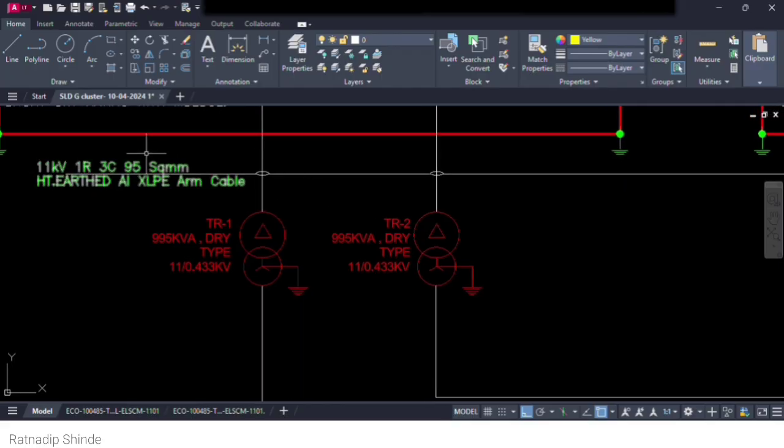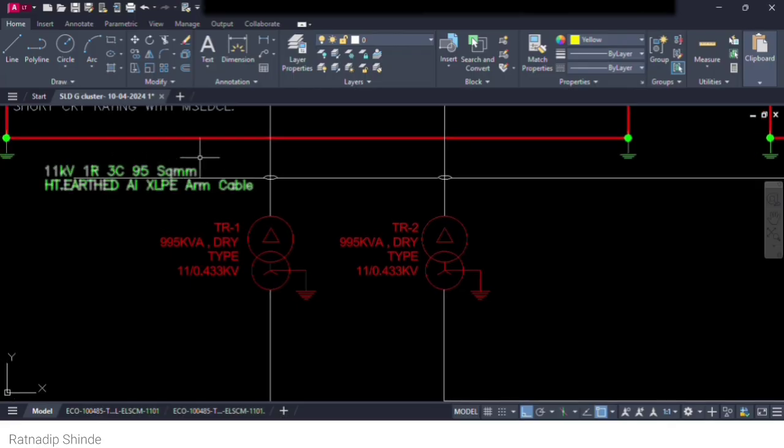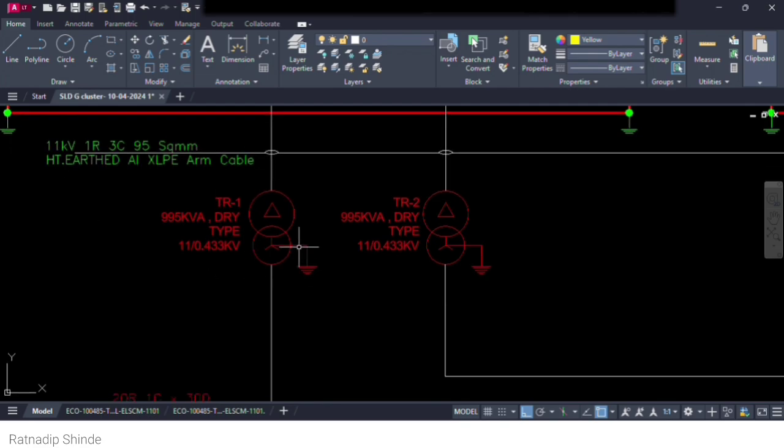Using that data we can calculate how many square mm of cable will be required. Now here we connected transformer 1, a dry type distribution transformer. This is a step down, delta star connected transformer. The primary is connected in delta and the secondary is connected in star with the neutral grounded. This comes under the vector group Dyn11.